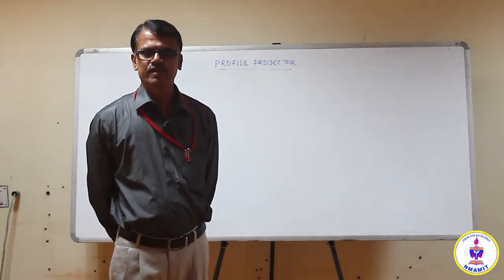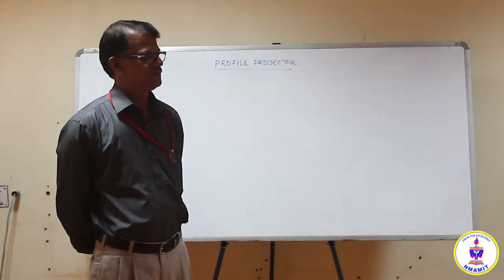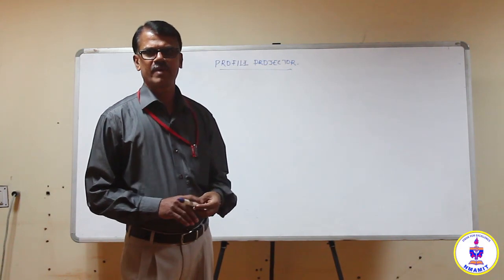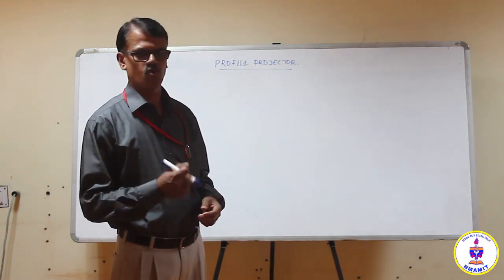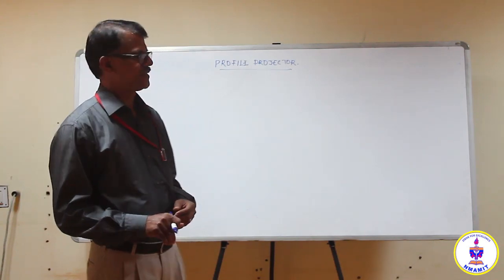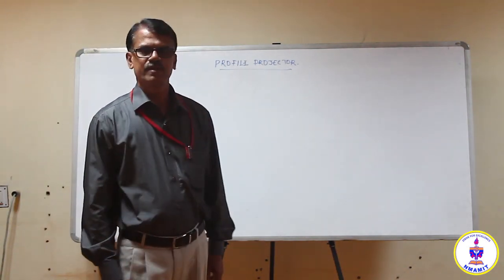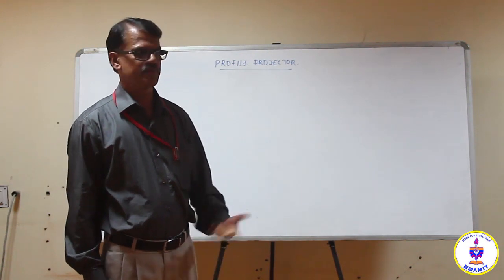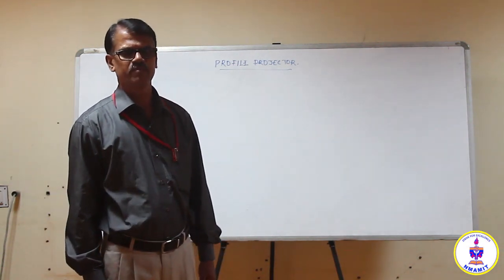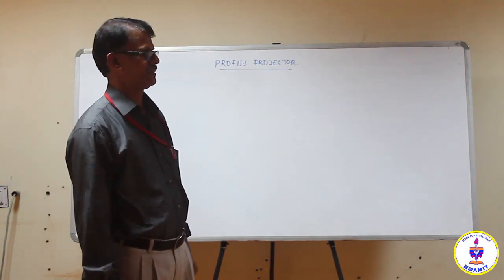Profile projector consists of an optical system that is used for projecting a magnified shadow of a small object onto a screen, so that direct measurement can be made on the screen, or it can be compared with standard profiles so as to make a comparative assessment.